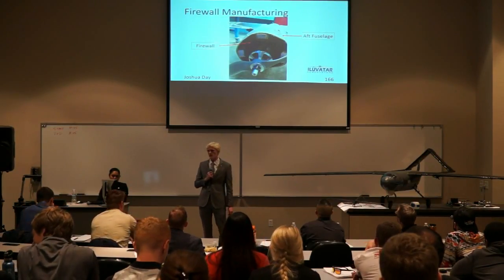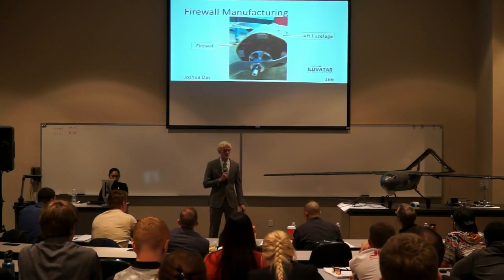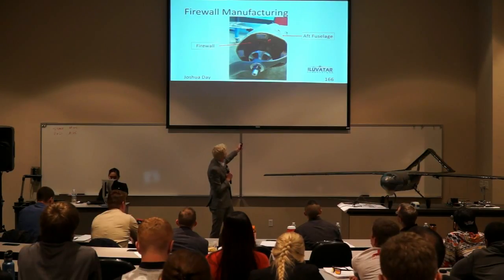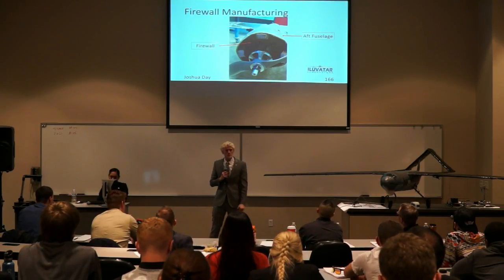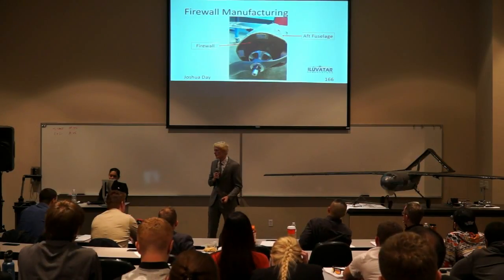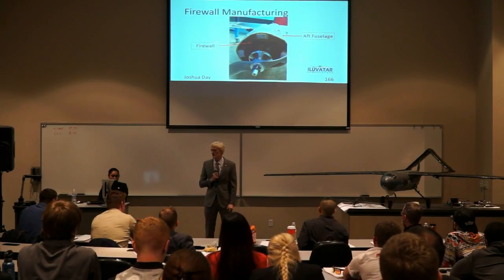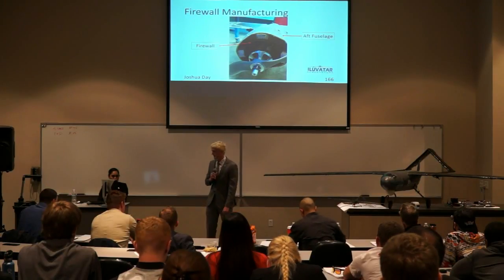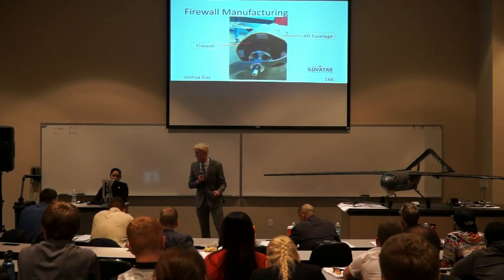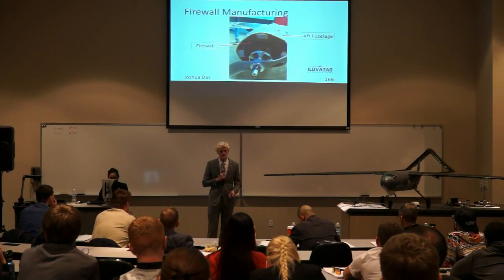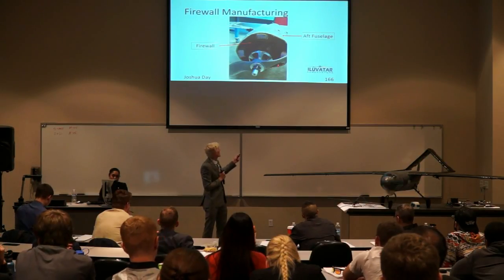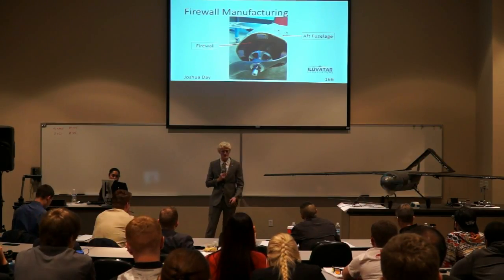The firewall was originally designed to be 1/8" plywood. It's within this section, it's a little hard to see. But due to availability, in the machine shop we used a 1/4" plywood, which would just be slightly over-designed. And then the firewall was attached to the fuselage using epoxy onto the longeron sections and the ramp. And the motor was attached.